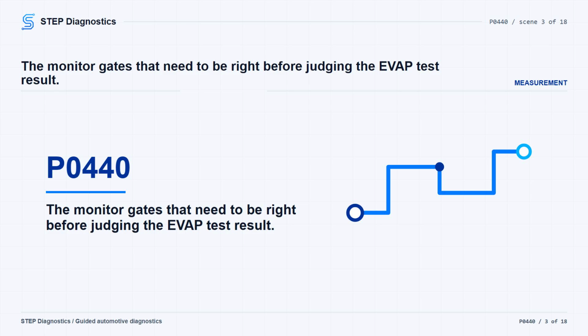The monitor increments accumulation fail timers until both calibrated thresholds are reached: engine on 100 minutes and engine off 70 hours. Also remember that temperature swings can fool the test. A rapid temperature change can create vacuum fast enough to hide a leak, or vapor buildup can make a sealed system look like it is losing vacuum too fast.